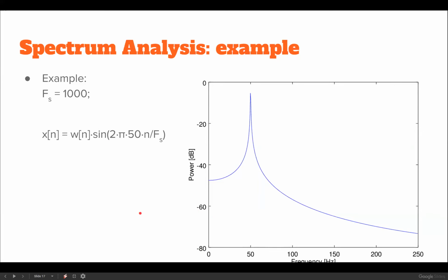But anyways, calculating a signal spectrum always has artifacts, because of the window through which you're looking at the signal. It has window effects, edge effects, Gibbs phenomenon, if you remember that one from engineering math classes. So basically this is what a single spectrum of a sinusoid would look like.